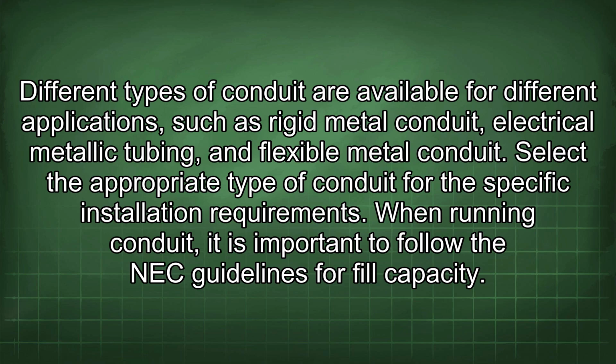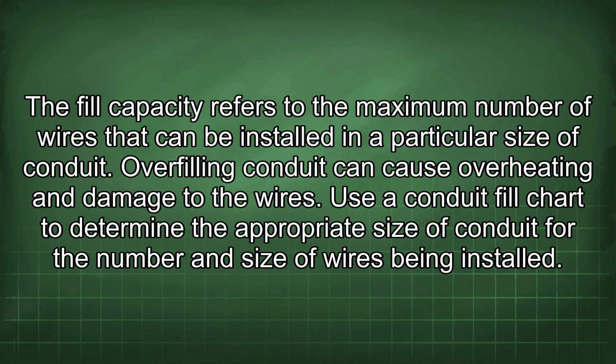When running conduit, it is important to follow the NEC guidelines for fill capacity. The fill capacity refers to the maximum number of wires that can be installed in a particular size of conduit. Overfilling conduit can cause overheating and damage to the wires. Use a conduit fill chart to determine the appropriate size of conduit for the number and size of wires being installed.